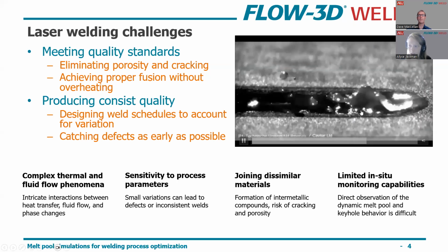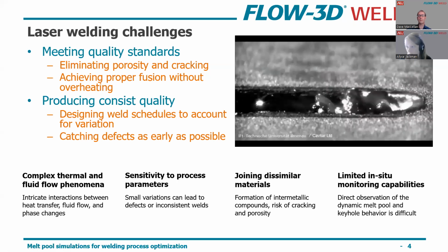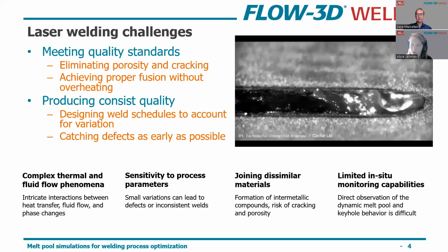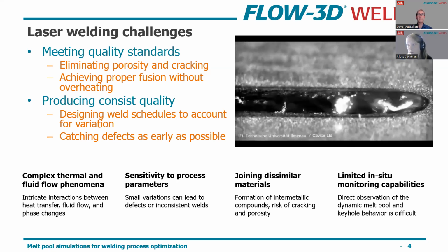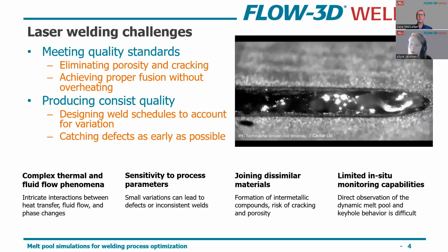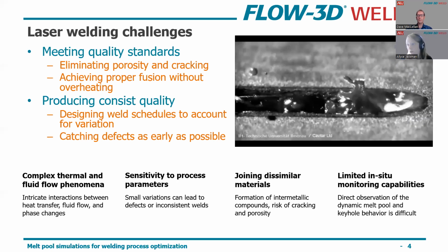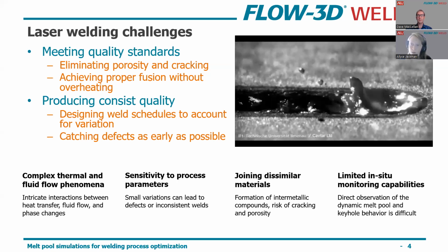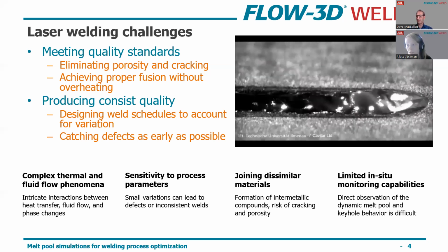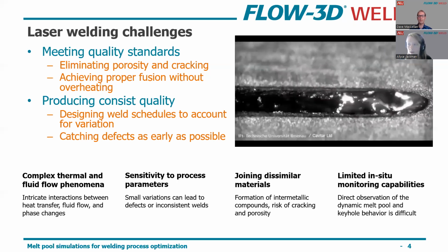So we can see this video on the top right. This is from a Cavitar camera, very nice high resolution capturing of this laser welding process. But despite the fact that we can very clearly see the fluid flow and the spatter, you can't get an indication of what the local temperatures are. You don't know what the thermal gradients are. You don't know where the solidification front is. You don't know the mass flux due to vaporization, how much material is getting evaporated. So these types of things are where we look to simulation to really understand more holistically what the implications of process parameters are on our process.